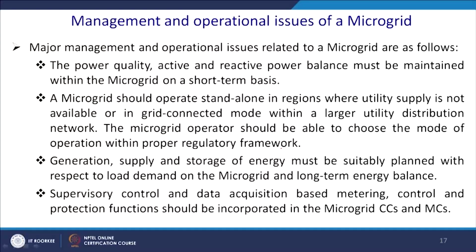Generation, supply and storage of energy must be suitably planned with respect to the load demand and the microgrid long-term energy balance. Supervisory control and data acquisition based metering, control and protection functions should be incorporated in the microgrid controls and the MCs.